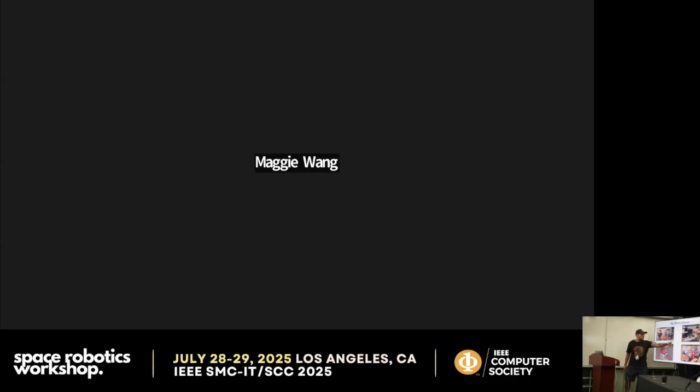The next video is from another 2 students in my lab. We put on propellers and even our own speed meters to see how many RPM we are generating from the FPGA board connected to the motors. Our idea was completely migrating the electronic speed controller into the FPGA by creating a PMOD with analog transistors connected to the fabric of the FPGA, so they replace the microcontroller inside the ESCs and become one of the IPs used.